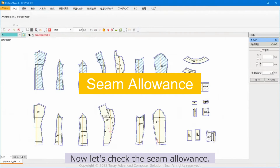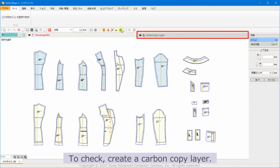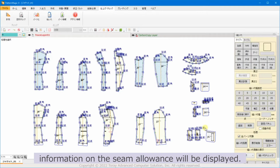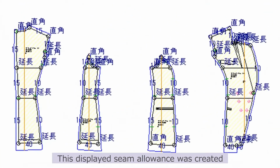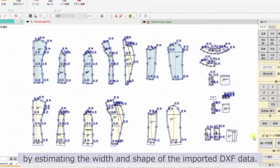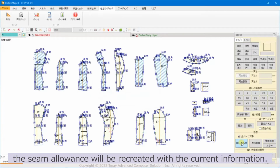Now let's check the seam allowance. To check, create a carbon copy layer. Select the seam allowance function. Information on the seam allowance will be displayed. This displayed seam allowance was created by estimating the width and shape of the imported DXF data. By clicking the seam allowance button, the seam allowance will be recreated with the current information.